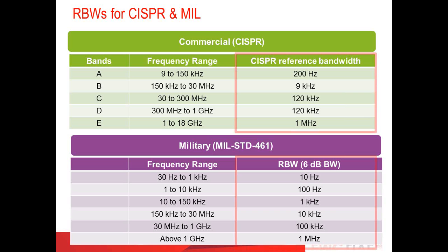So sensitivity is a function of the bandwidth of the IF filter, but it's also a function of the attenuator. You can see here two diagrams. As we change the attenuation from 10 dB to 20 dB, the signal level is not changing. And remember, I said that's because we actually compensate for that on the other side of the mixer. So that's important: signal level does not change as a function of the settings.